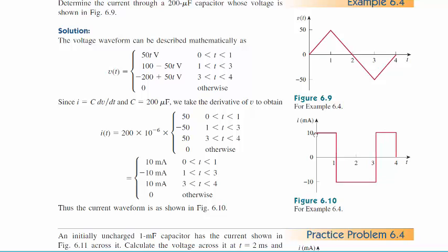So what it's saying is that the current can instantaneously switch. So it's 10 milliamps when the voltage is increasing across the capacitor, which would be like when the capacitor is charging up, and now the voltage is getting smaller across the capacitor, implying that the capacitor is discharging, and so discharging is reversing the current direction, but look at this maximum value in the other direction of current.